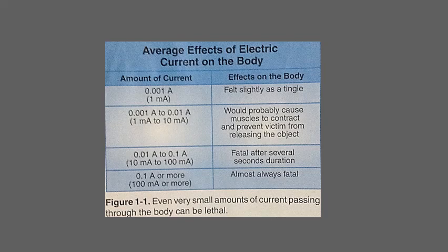The second type of electricity-related burn is a result of an arc flash. Arc flash is the explosion that takes place when electricity short circuits through the air or across inadequate insulation. The temperatures during an arc flash are high enough to melt metal. An arc flash projects melted metal outward, injuring any unprotected workers in the area. The best way to prevent an arc flash is to de-energize the equipment before working on it. If this is not possible, be sure to wear the appropriate clothing and eye protection.